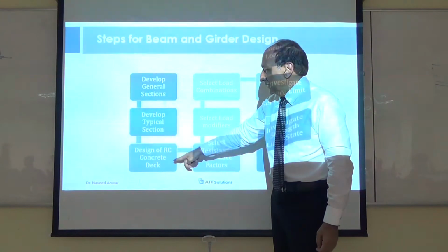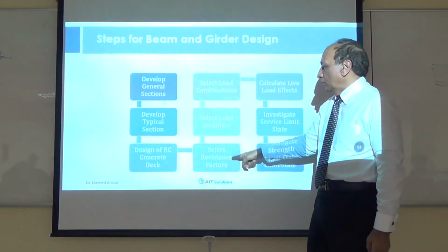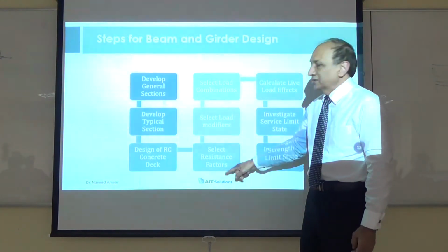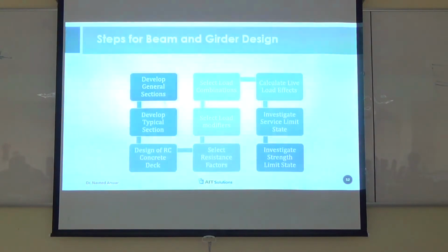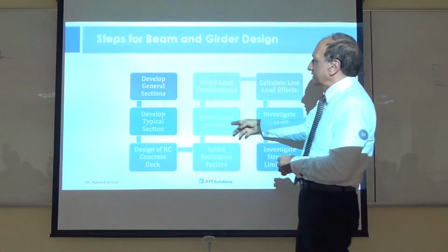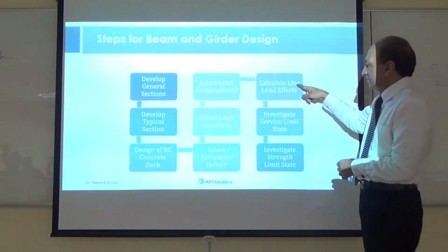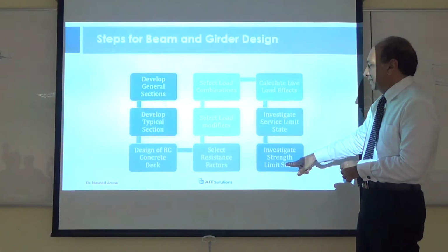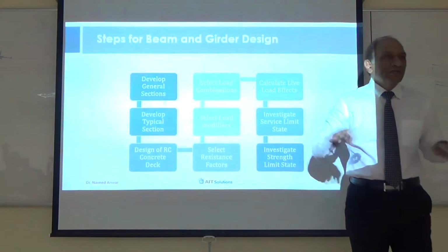Then from typical, then design of the RC concrete deck. So we start with the deck first, then we go to select the various resistance factors for the design purposes, select the load modifiers, then select the load combinations, then calculate the live load factors, then investigate the service life limit and investigate the strength limit. So typically we go into that step by step into the design.